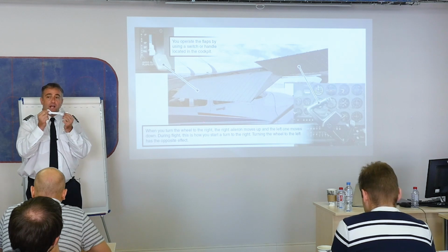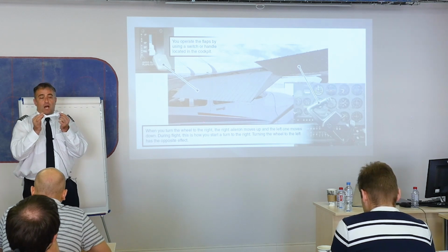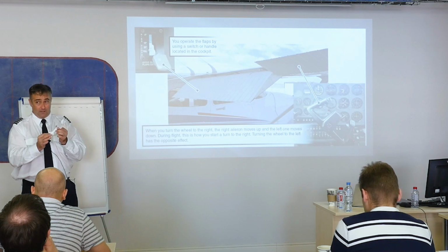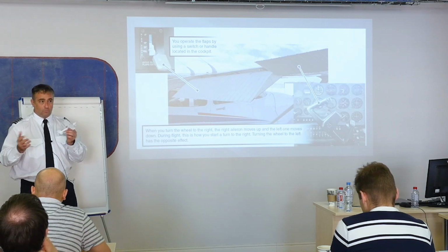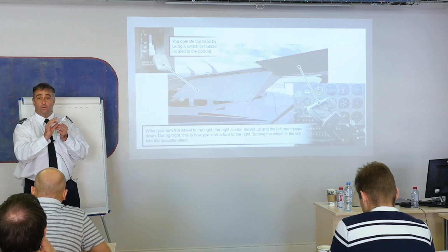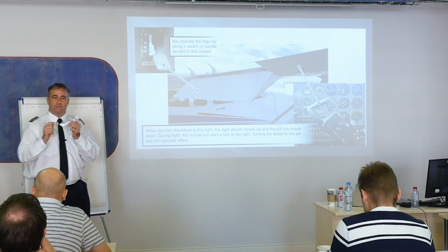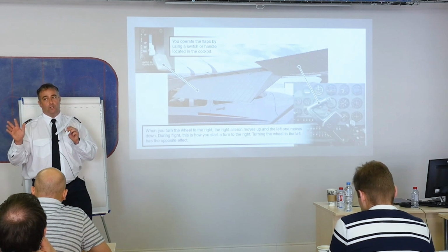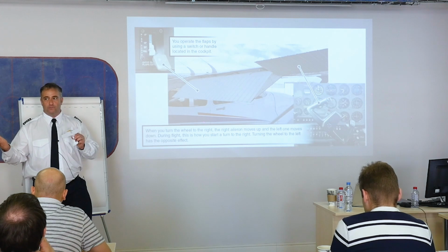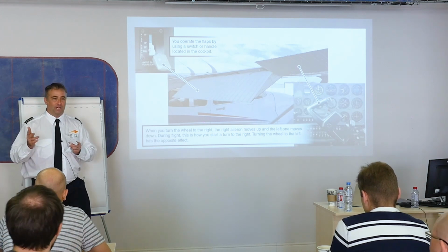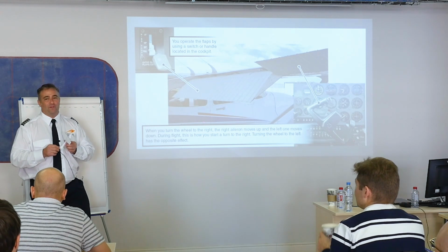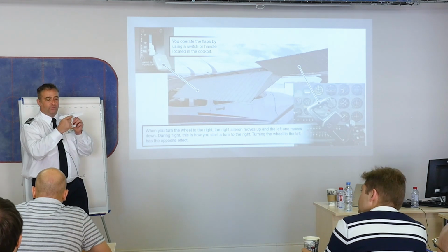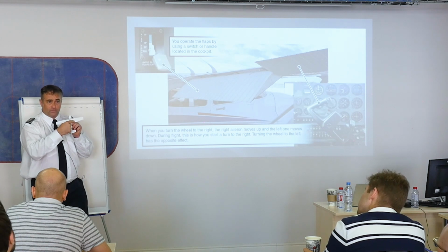Depending on how fast I'm flying this airplane in level flight, I may be very close to no longer being able to support the airplane in the air. There's a condition called a stall, where the airflow separates from the top of the wing, and I no longer produce enough lift to keep it flying. When the airplane stalls, it's also designed, these engineers are pretty good at what they're doing, and they have a complicated mess of problems when they start. I started in engineering school. I understand and have some sympathy for some of the engineers. But one of the things that they did is they built this wing in such a manner that it will stall here first.